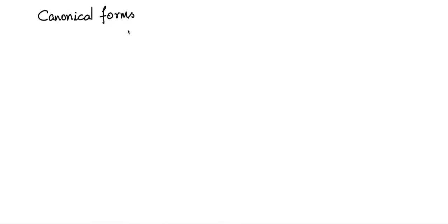Canonical forms. Let us discuss this. This is an important topic. We need to relook at the filter block diagrams, FIR and IIR filter block diagrams, and see if we can rearrange the blocks to a standard structure called the canonical form. And why should we do that? So let's have a look at a typical example. I will take a first order system as an example first.